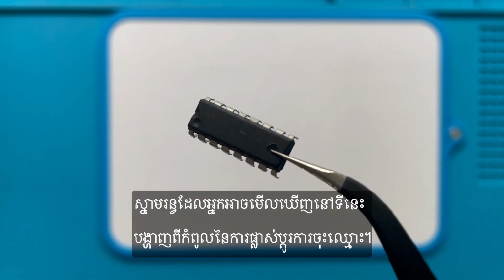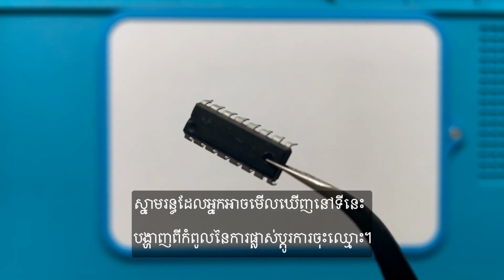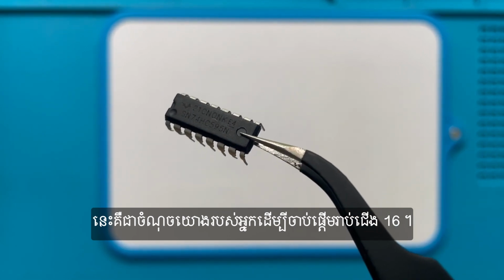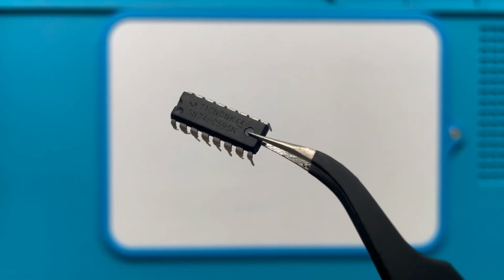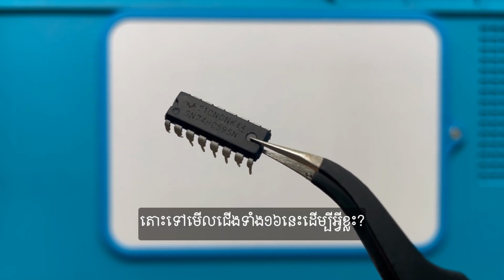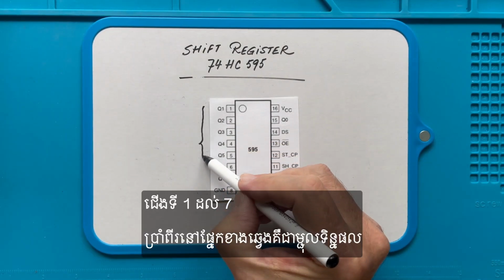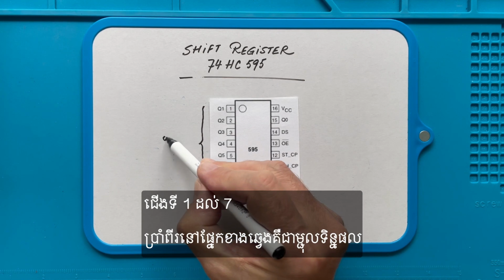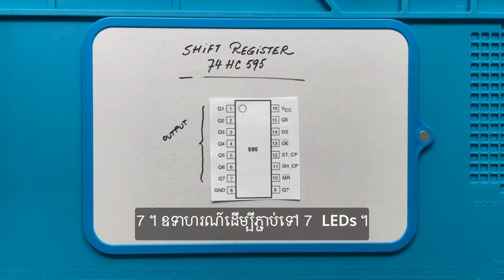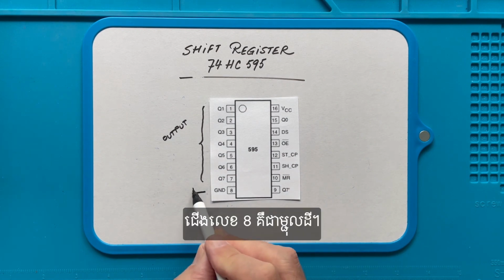The notch that you can see here indicates the top of the shift register. This is your reference point to start counting the 16 legs. Let's have a look at what these 16 legs stand for. Legs 1 till 7 on the left side are 7 output pins, for instance to link to 7 LEDs. Leg number 8 is the ground pin.